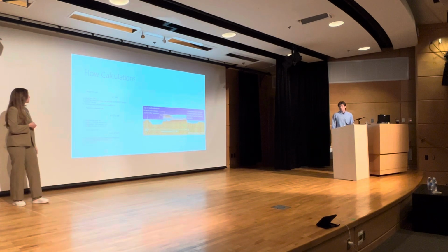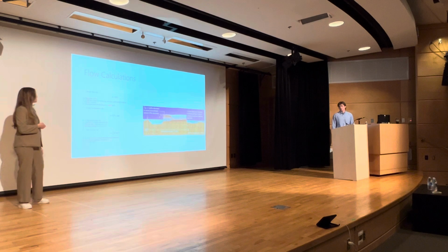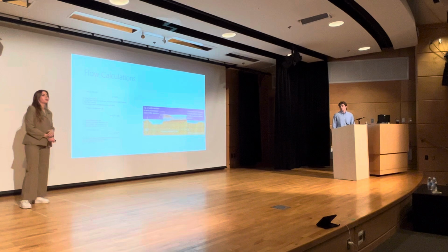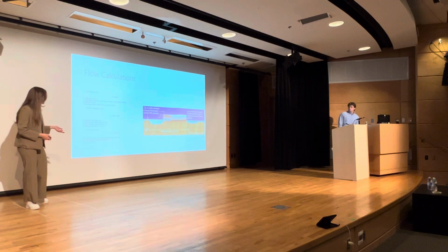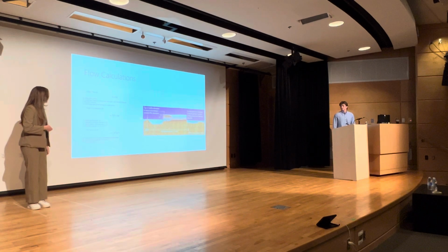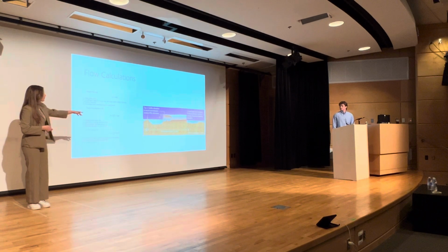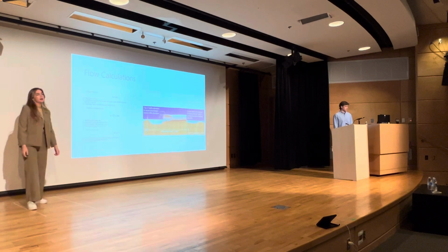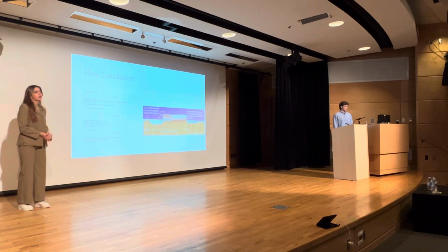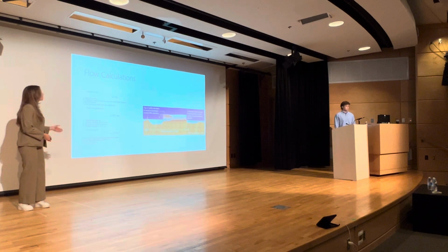It's Q equals CIA. C is the coefficient based on land use, I is the rainfall intensity, and A is the drainage area contributing to runoff, which is basically our watershed. Then it's our slope consideration. Our slope will be from the downstream controlled riffle elevation to our upstream elevation. This is just where the velocity is the highest, and that is where the velocity is the lowest. We will divide that by the length of that area, and that's how we get the slope. And for the flow velocity, it's just Manning's equation, but I'm sure that this will change in our future research, and we will have to talk about that with our industry partner.